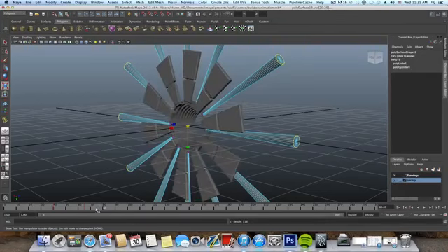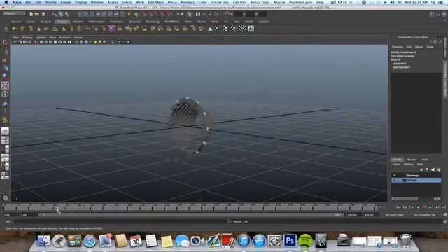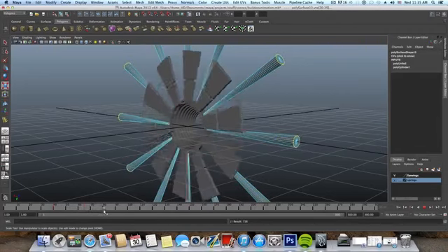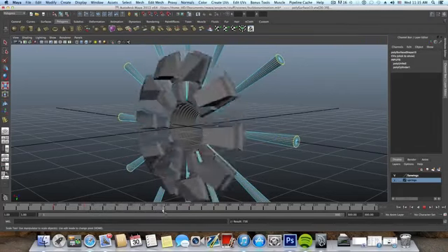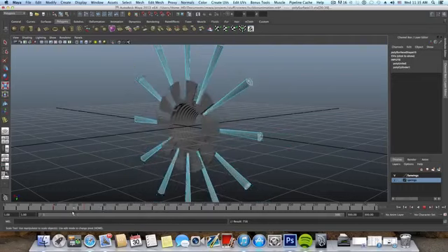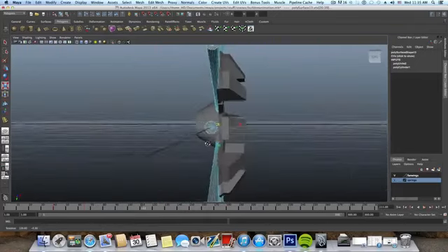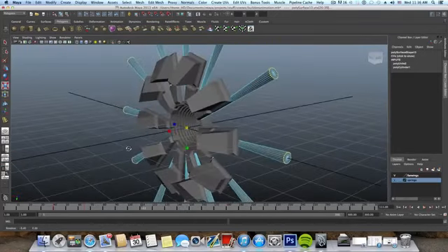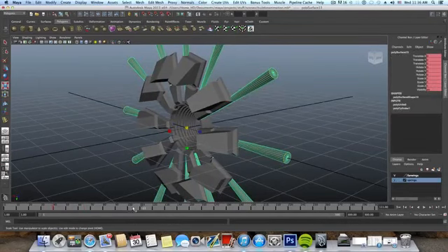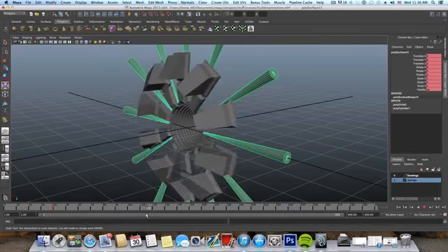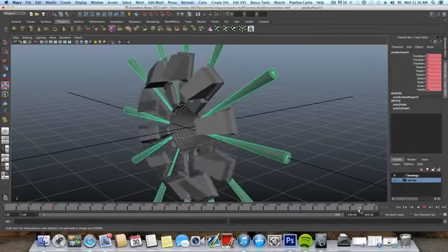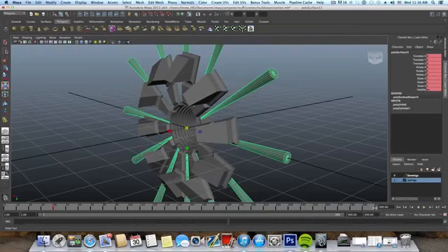Okay. See? Simple as that. Now, you can also tap F8 to bring it back to object mode, and if you want, you can add a little bit of rotation to it, so just grab it back immediately to frame number 300, and again, we will use the rotate tool with snapping, hold down the J, and just start rotating this axis, like so.